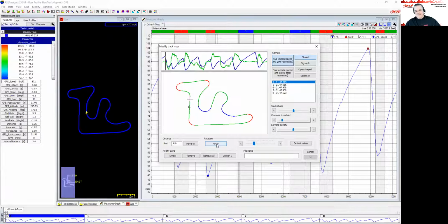Okay. And then finally, now that we've gone over some of those, and I'm going to watch the chat and the Q&A, I want to do the next step, which is to use that bar across the top, those little strip charts, and build a track map that works for you. Instead of using the AIM default values, let's build one where we end up with track map segments, maybe only 3, maybe 4 segments for the entire track, because I don't want to know every corner. What I really want is the way that you would drive a track.